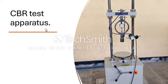And next is the CBR test apparatus, which costs around 83,000 to 2,49,000 depending on configuration and accessories. Its function is to evaluate the strength of subgrade soil and base course for road construction. And its principle is to measure the resistance of soil to penetration by a standard piston under controlled moisture and density conditions, expressed as a percentage of standard materials.